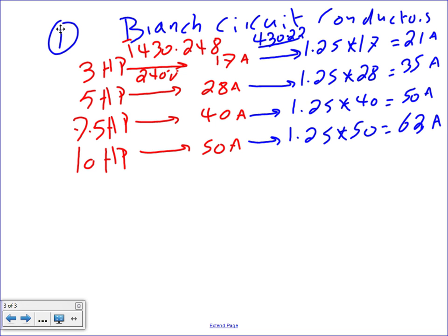The last thing we're going to find, my friends, is the conductors. Let's take the 21 amps to 310.15(B)(16) under the 75-degree column, and I need a smart individual to tell me why there and why this amps. Why do we go there? And why 75? They're motors. For the most part, they're 75.